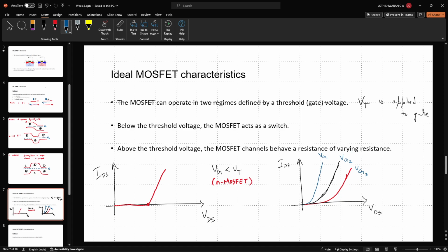And this tells us that the resistance, or rather the conductance, G for this will be given by dV ds by di ds. So dV by di. For a linear thing, dV by di is a constant, so we will just write it as delta V by delta I. And at a given point, we will even write it as V by I if it is completely linear. In this case, we will write it as delta V by delta I. But over here, we'll have to evaluate the derivative at any given point. And as you can see, the value of the derivative changes depending on where we are on the curve. This is not a linear curve.